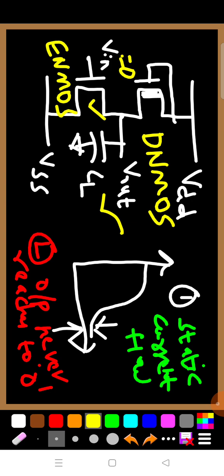Sorry, when Vin is equal to 0, this pull-down device will be turned off, then this depletion mode NMOS is always in on condition, therefore the capacitor charges. And when Vin is equal to 1, you can observe very clearly that this transistor, because it is an enhancement mode transistor, will be turned on. Then what will happen? Then the capacitor discharges to 0.